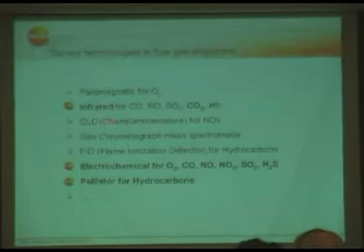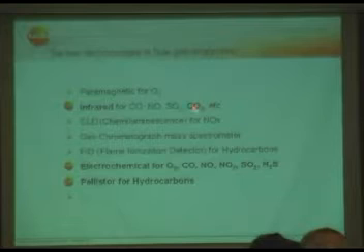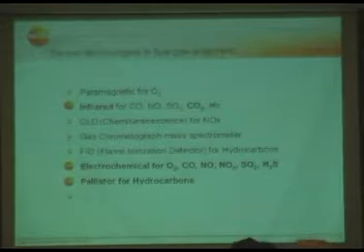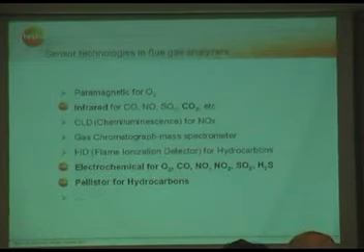Yes, there's paramagnetic for oxygen measurements. There is infrared for CO, NO, SO2, CO2. TESTO uses infrared for the CO2 sensor. This is also important because especially at the cement plant you will have CO2 because of the fuel you're burning.